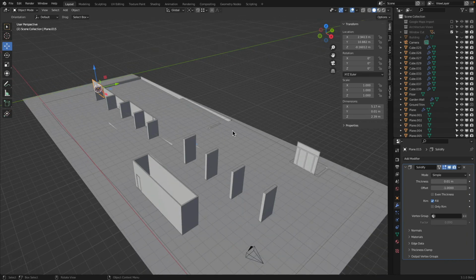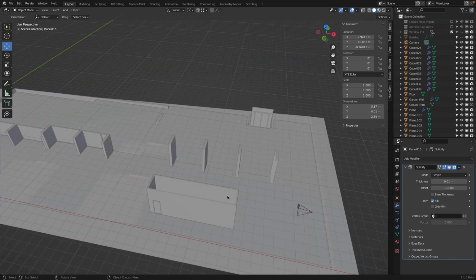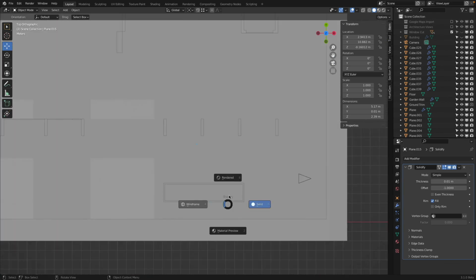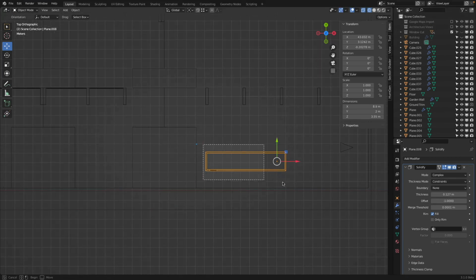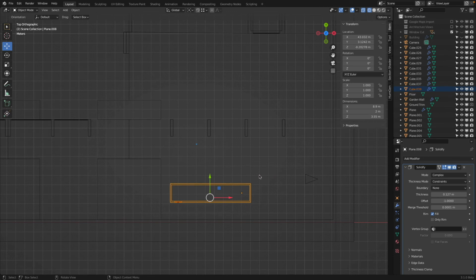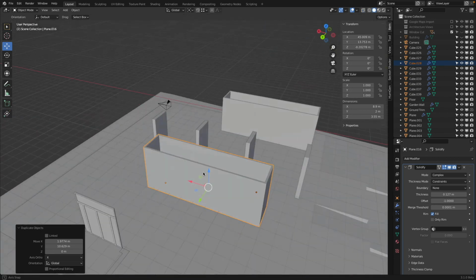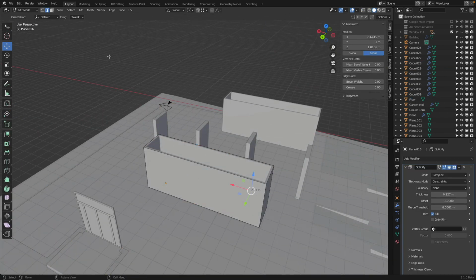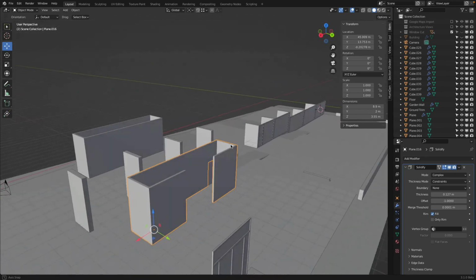Very good. If this is an open piece and we would like to create a structure that is maybe open, we could, for example, Shift D and just do a piece here so you can see how this works. I would then go into edit mode, Control R, there, and remove these edges. Look, now this is open.